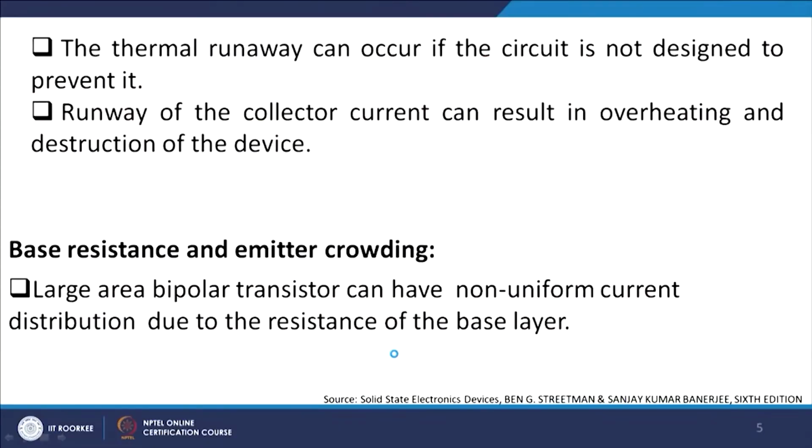So, your overall collector current will reduce, and therefore your gain will reduce. That is the reason why you have a reduction due to increasing transit time as the temperature increases, and this is one of the problem areas which people face.